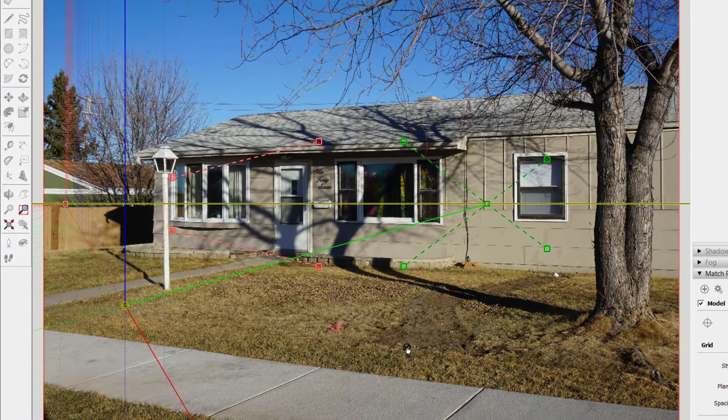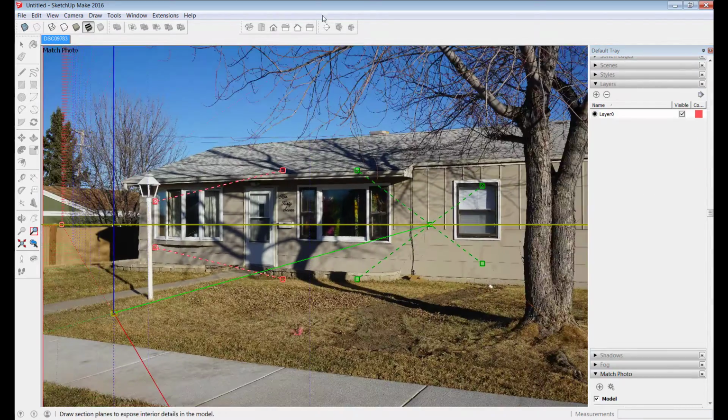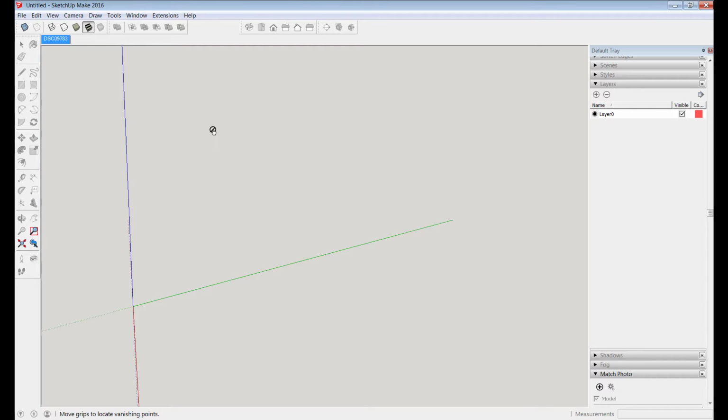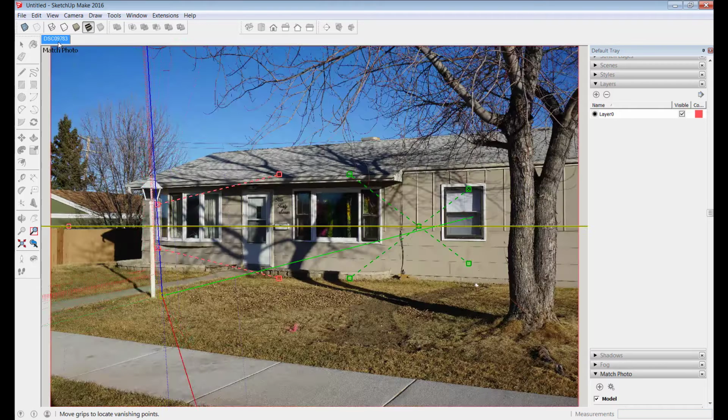Some viewers may have seen the Photomatch example I did doing a fireplace mantle for an interior scene, and this is similar, only it's the exterior instead. I'm going to choose the outside frame of reference for this particular model, although I really haven't been able to discern noticeable differences between those three styles that show up. Something to remember when working with Photomatch is that scrolling in and out with the mouse wheel works great. I use a 3D mouse, and if I touch that at all, you can see the photograph disappears, but it's brought back by just clicking the photo tab.